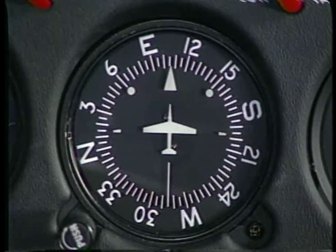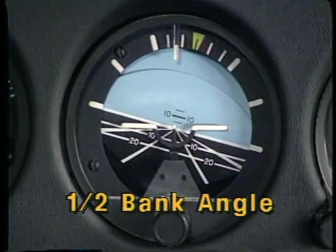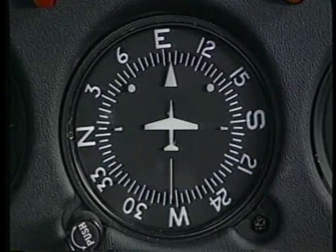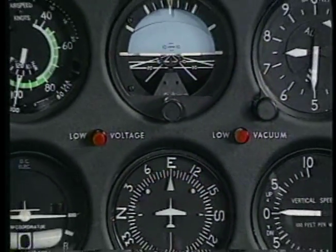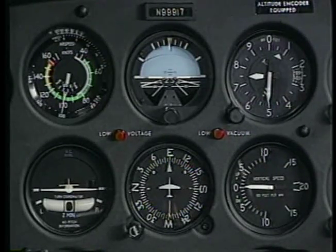To allow for the roll out, lead the heading by the number of degrees equal to 1/2 of the bank angle. For example, if you are in a 15-degree bank, start the rollout about 8 degrees before the desired heading. As you return to wings level, release the back pressure held during the turn and continue your instrument scan.